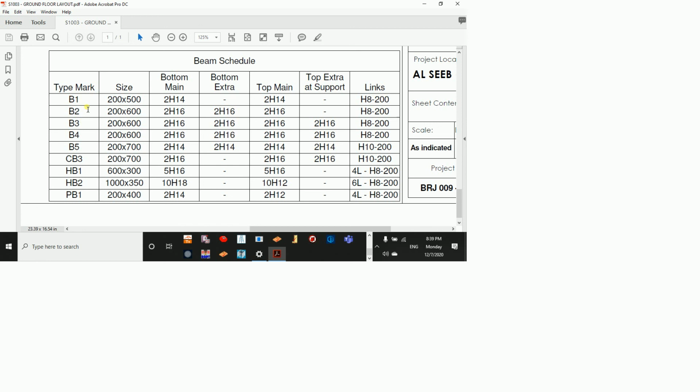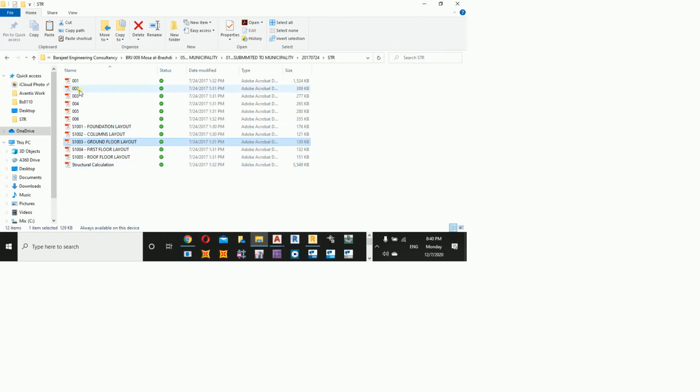The other category we call B2. And you can see one difference is the size between the beams, and the other difference is reinforcement. Like here, for example, between B3 and B4, they are exactly the same, so there is no point of having B3 and B4. L is how many legs in the case of a hidden beam, where we are talking about the links.